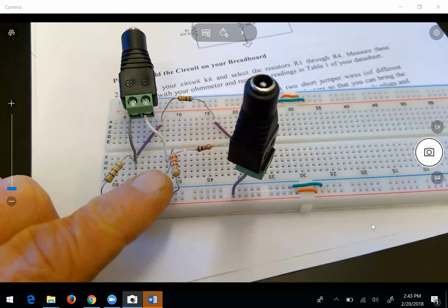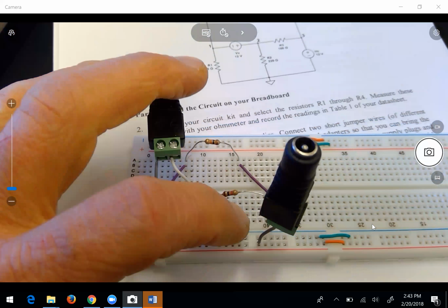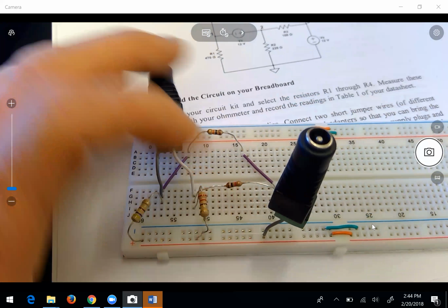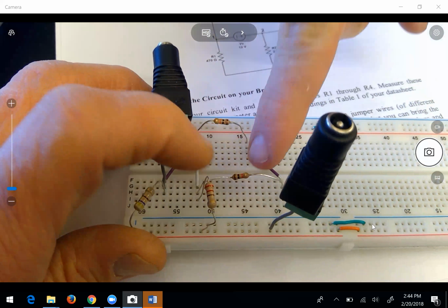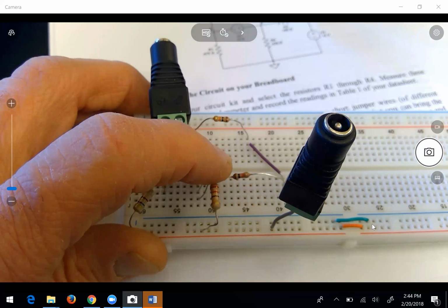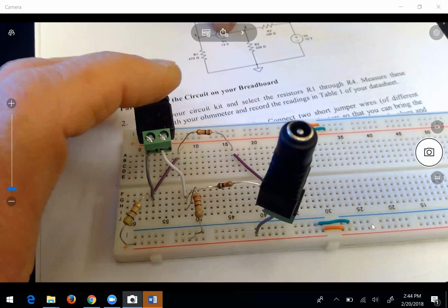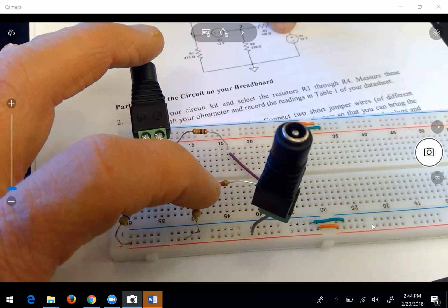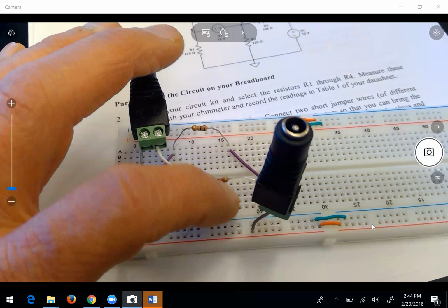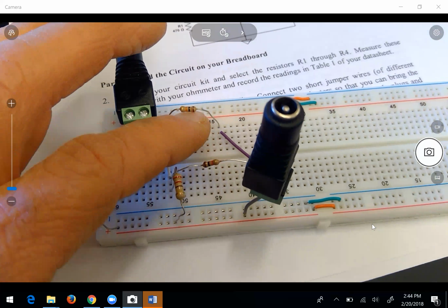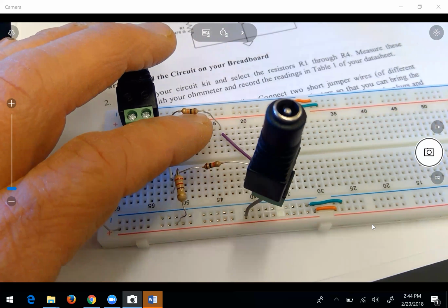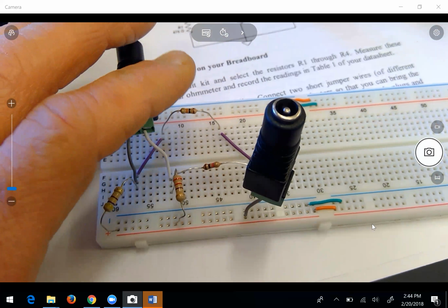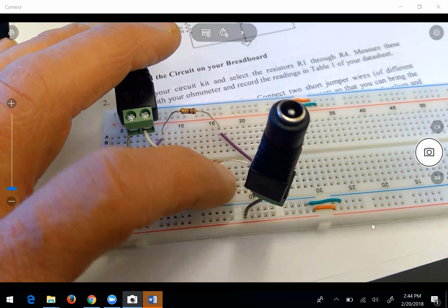And then the 220, is that a 1K? This is the wrong resistor value. That's red, but the color code for 100 ohms is brown, black, brown. It's 1, 0, and an extra 0. In other words, brown for 1, black for 0, and brown for an extra 0. This is 1K right here, and this is 10K, which is brown, black, orange. The resistor that my finger's on right now should be removed, and you should find the brown, black, brown color bands to go right there.